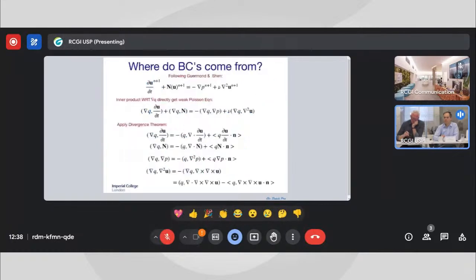What did I do when I had my terms? Here, I have my Navier-Stokes equations. I multiplied them by this gradient of Q term. We'll see why that helps us in a moment. And then I've got these rounded brackets, which just meant I integrated over everywhere I want to solve my problem in. And now I'm applying the divergence theorem.